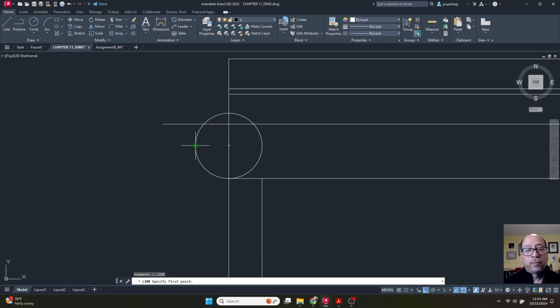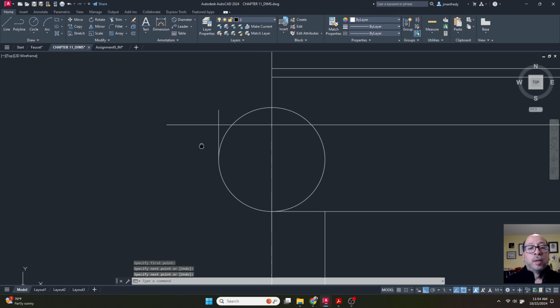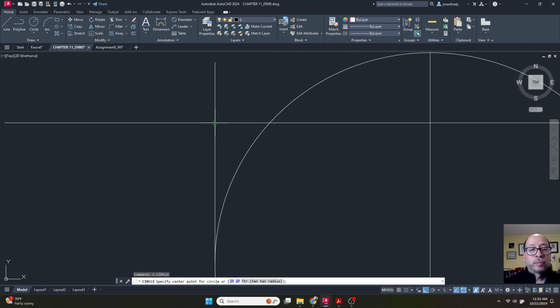I'm going to draw a line from this up to there, because what's happening here between this point and this point, that last final corner there is going to be another curve. And that curve, they're saying it's going to be a 1/4 inch. Let's make sure, confirm that distance. DIST between this point and that point there. They're saying it's a half. So this is going to be a 1/4. So I'm going to draw a circle from this intersection. And the radius is going to be a 1/4 inch.